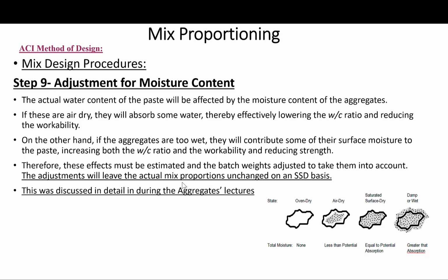So the effects must be estimated and the batch weights adjusted to take them into account. Okay, so the adjustments will leave the actual mix proportions unchanged on an SSD basis. Again, we discussed this, if you refer back to the aggregates lectures, we discussed this more in detail.